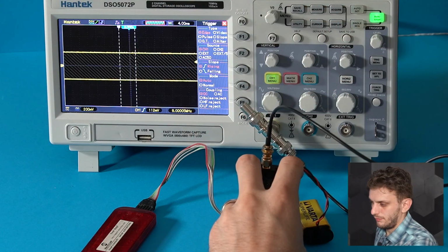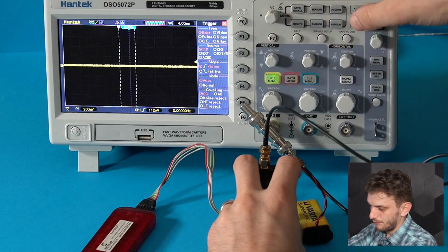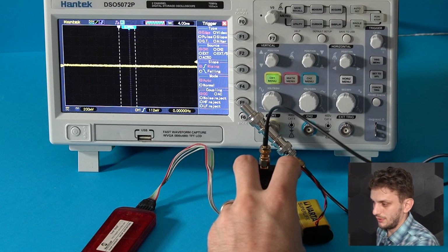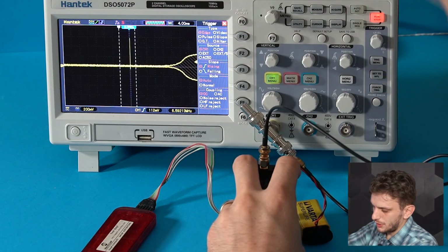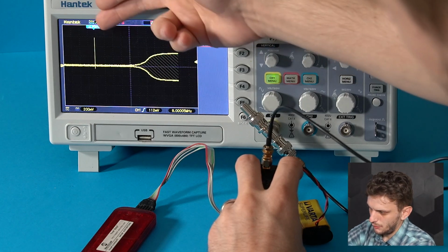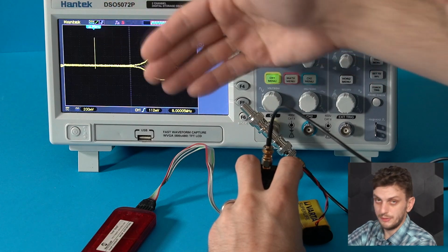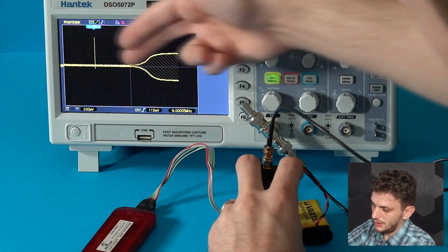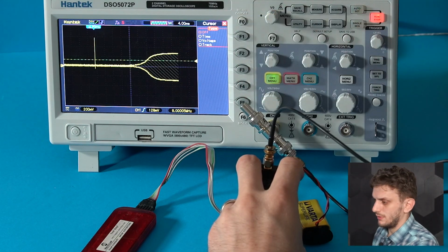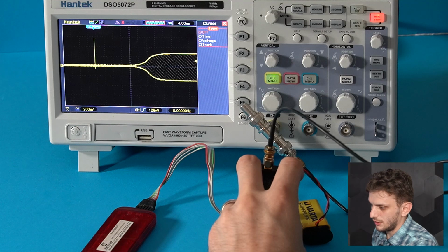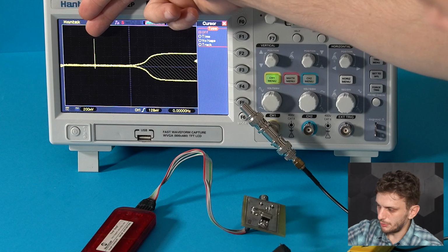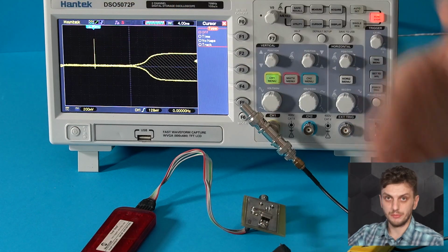So now I'll turn off the oscillator, set the oscilloscope into single mode, so to trigger on the rising edge of the input signal. And when we turn on our oscillator, so let's just move things around a bit, we see our startup pulse, so this is where the power is supplied, and then we see the oscillation slowly building up. So let's just make another oscilloscope capture, another startup, and now we can more clearly see what's going on. So we have our startup event, and then we see the oscillation building up.